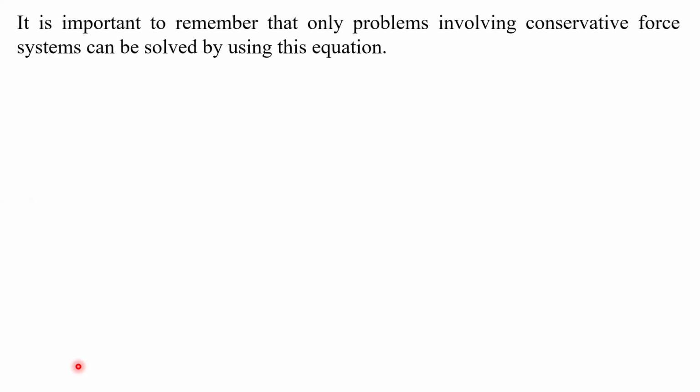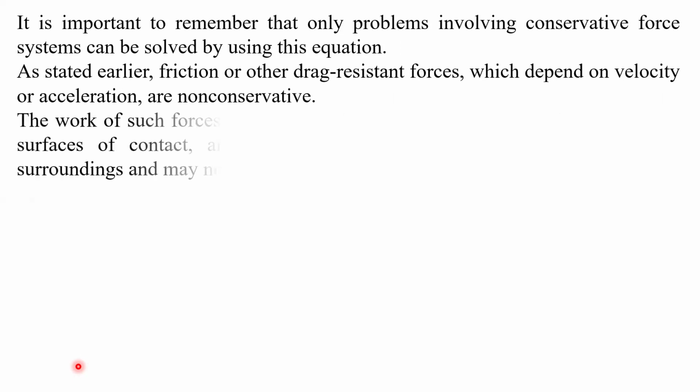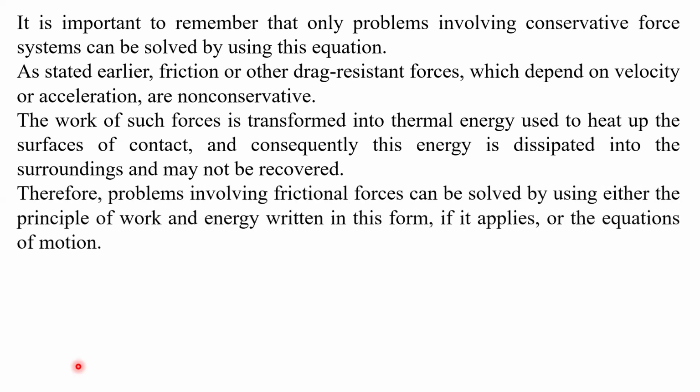It is important to remember that only problems involving conservative force systems can be solved by using this equation. As stated earlier, friction and other drag-resistant forces, which depend on velocity and acceleration, are non-conservative. The work of such forces is transformed into thermal energy used to heat up the surfaces of contact, and consequently, this energy is dissipated into the surroundings and may not be recovered. Therefore, problems involving frictional forces can be solved by using either the principle of work and energy written in this form, if it applies, or the equation of motion.